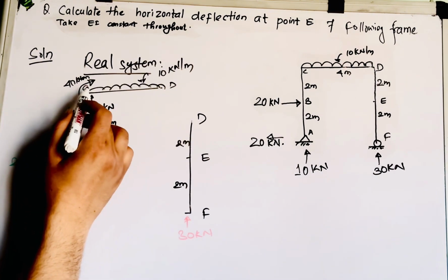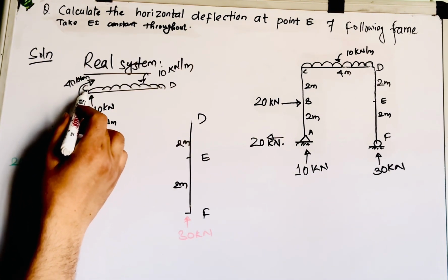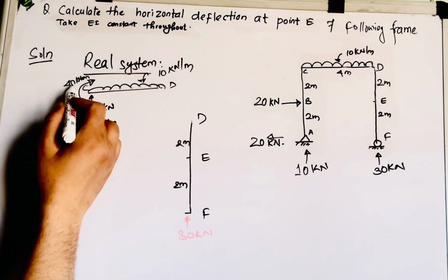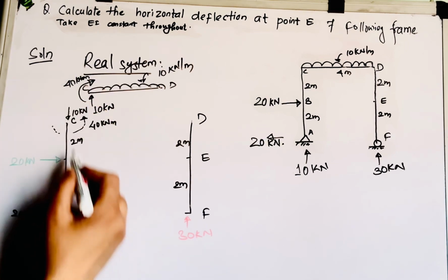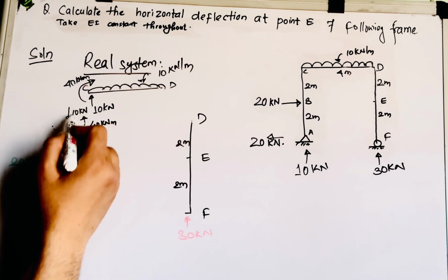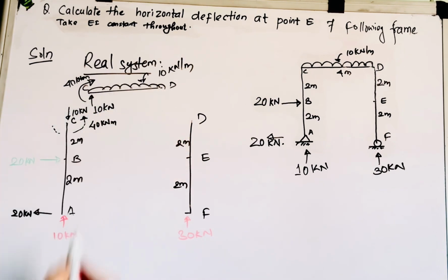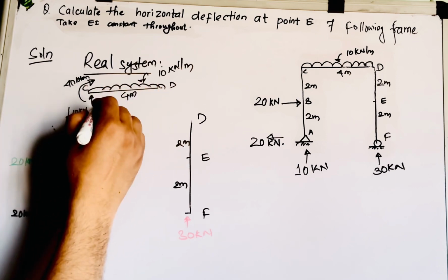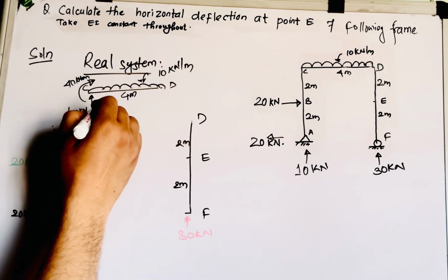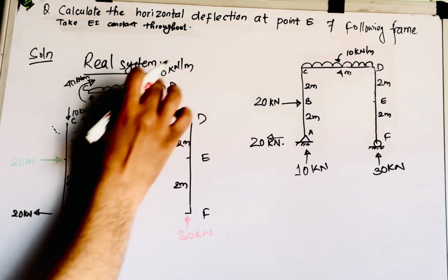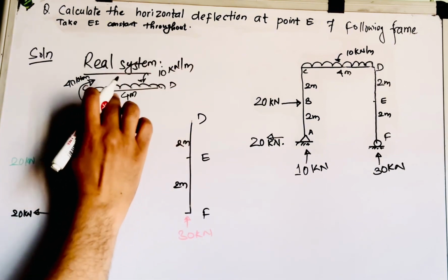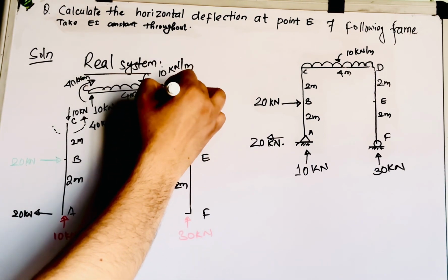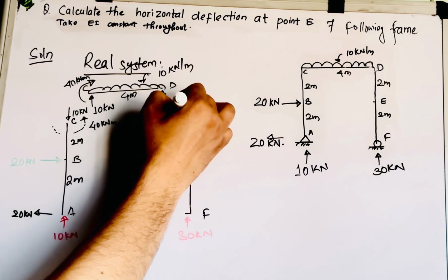Now there has been a transfer at point C or joint C. So joint C receives 40 kilonewton meter from this section, and 10 kilonewton is balanced like this. Now at joint D, what will be the shear force, what will be the axial force, and what will be the moment? You have to calculate like this. Since this is 4 meter, let us make a balance of the shear force. So 10 into 4, 40 downward, 10 upward. So to balance this, you have to write 30 kilonewton in the upward sense.